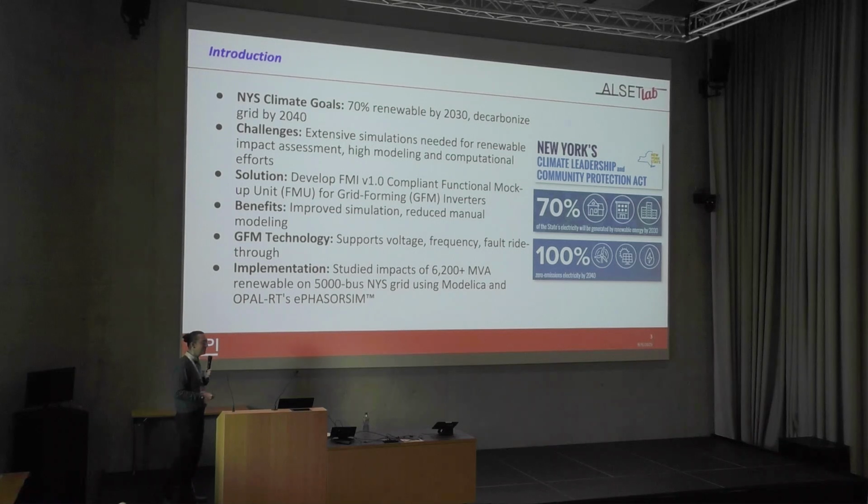ePHASORSIM gives you two choices. If you want to add a model that doesn't exist in their library, you can build it in Simulink and then copy-paste it as many times as you need, or you provide an FMU and you parameterize it in an Excel file. They talked to me because doing it with the Simulink approach was a nightmare for adding this new model that doesn't exist in their library. So they needed somebody to build that model, and they needed very simple functions that the model can represent.